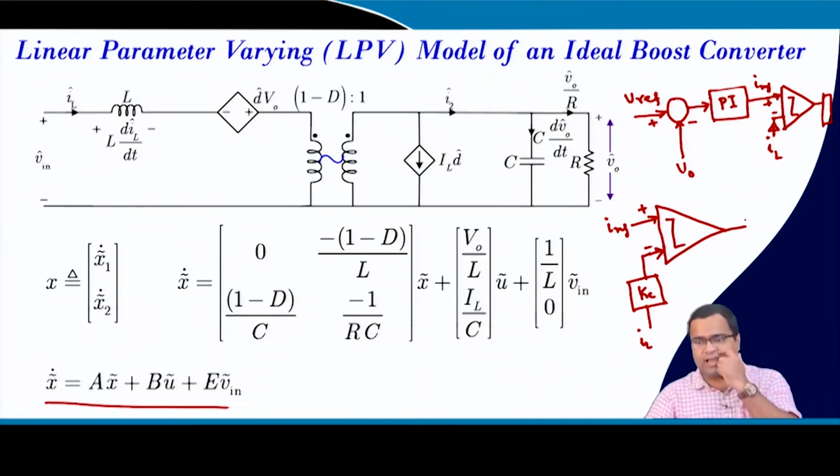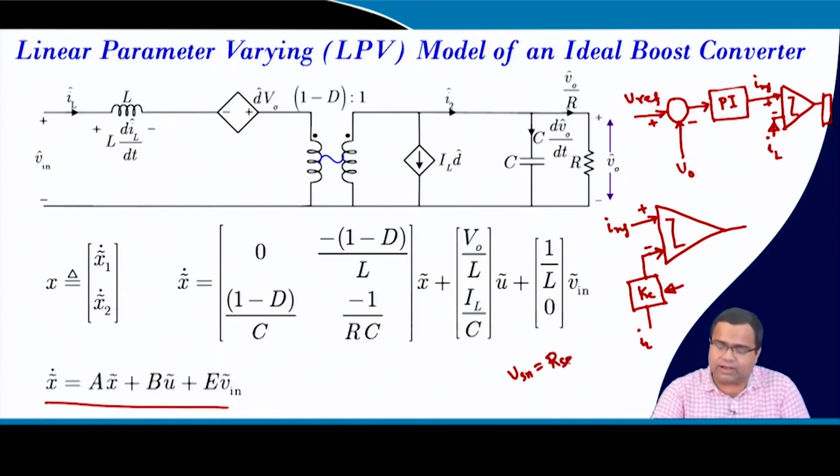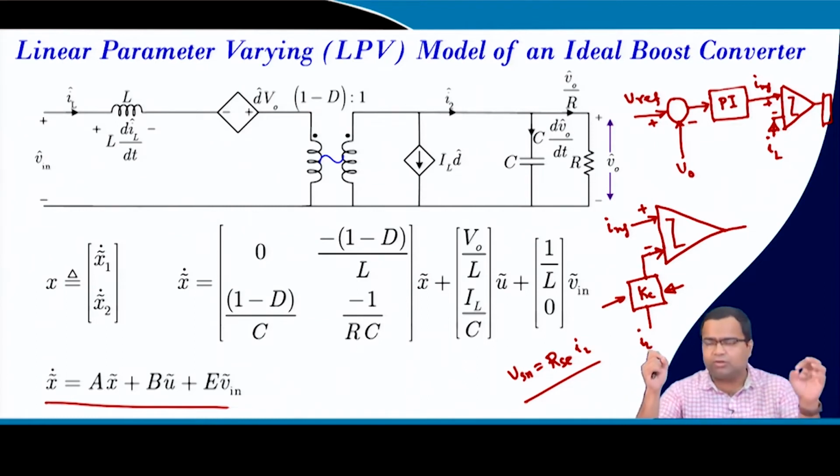And again it goes to the latch. So, this current loop gain can already be placed, because we said the sense voltage of the inductor current is the RS equivalent into IL. So, it is coming from the sense resistance. Sometimes we need to intentionally change the gain to do some optimization, and that is very much possible in digital control, as well as in analog, although it is difficult, but it is possible.